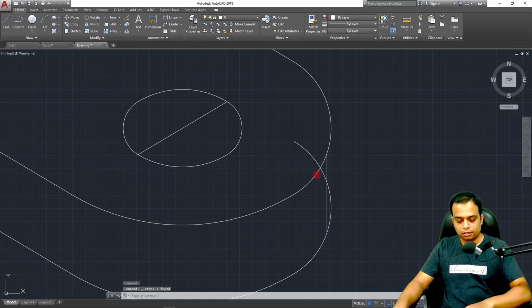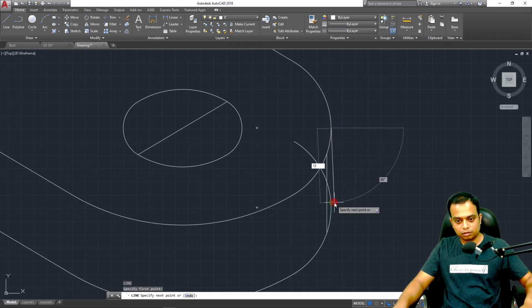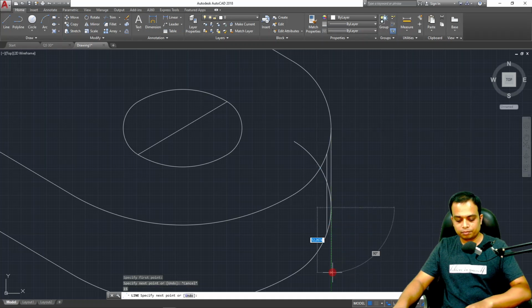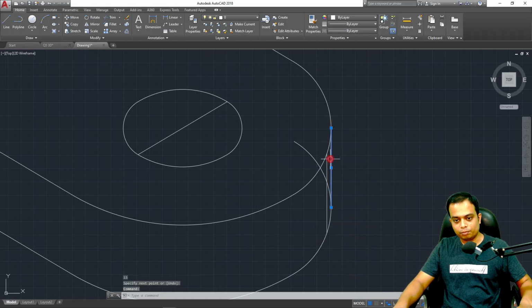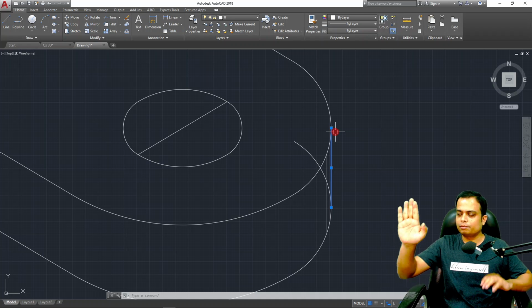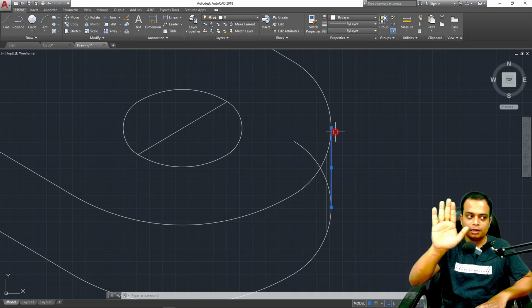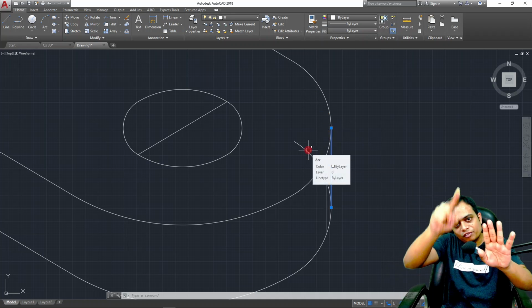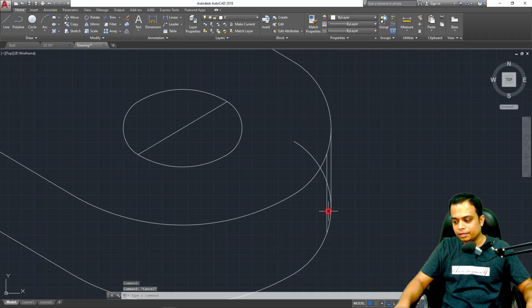All right, line somewhere here, 15 mm downwards. No, no, no, not this way. 15 mm. The point that I've selected to make this line is almost on the extreme right hand side of this curve. That is the point that you need to select. Make sure your drafter is absolutely vertical. Bring it to this portion, and the moment it becomes absolutely tangential to this curve, drop a line 15 mm below, and obviously it is going to cut here. That's for sure. Okay, let me erase this.